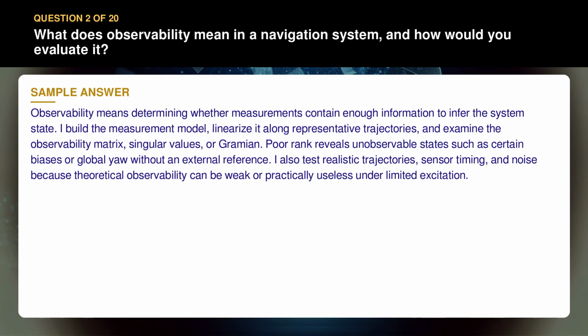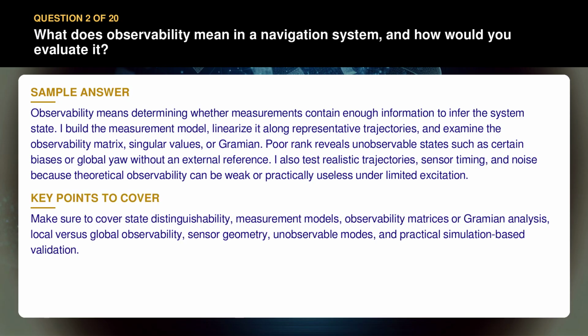I also test realistic trajectories, sensor timing, and noise because theoretical observability can be weak or practically useless under limited excitation. Make sure to cover state distinguishability, measurement models, observability matrices or Gramian analysis, local versus global observability, sensor geometry, unobservable modes, and practical simulation-based validation.